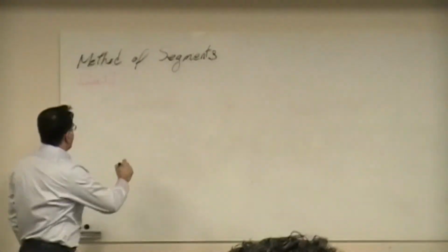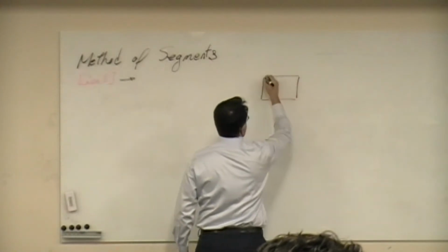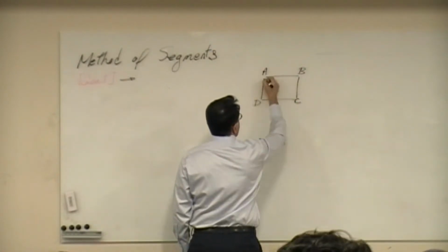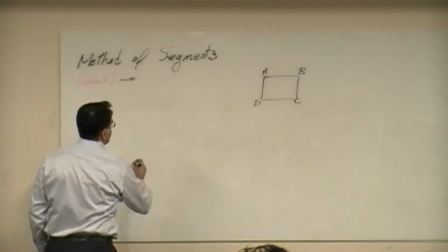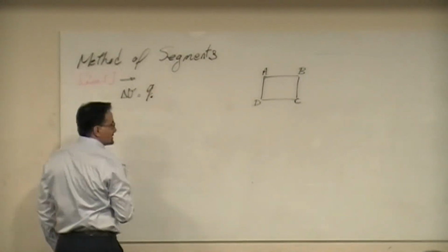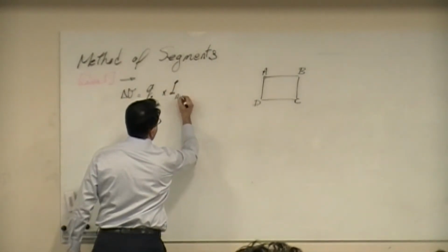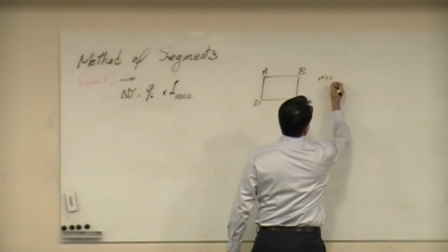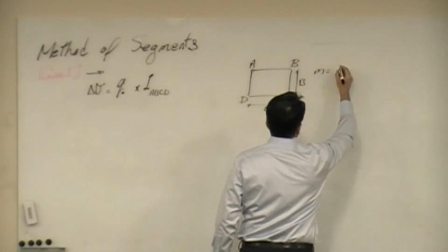So case number one. This would be for the case that you want to calculate the stresses at a corner of this rectangular shaped footing. That's A, B, C, D. And let's assume that I'm interested to calculate the stresses at point A. How do I do that? I just saw that you can calculate delta sigma as a function of Q naught times I. And that I is associated with I for A, B, C, and D, right? In this specific case, you have the N value, which is L, let's call this one B here. What was the M and what was the B?